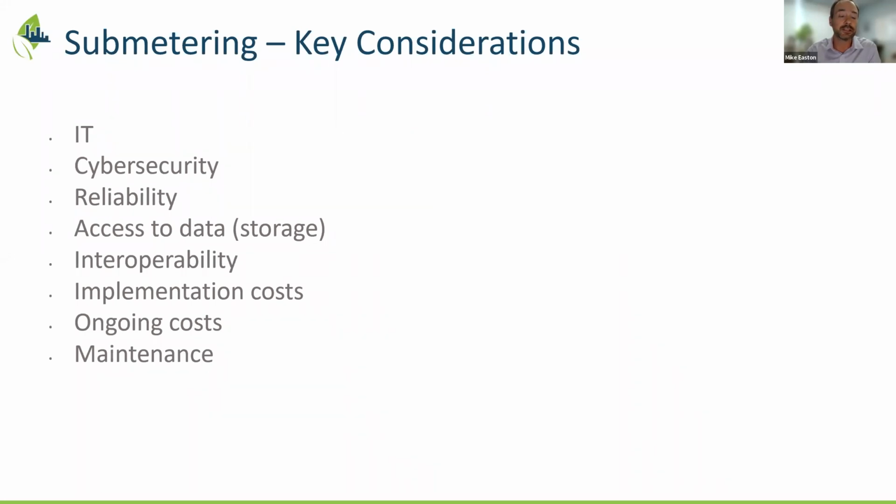which again seem to be very utilized these days. If you are going to be doing a web-based solution or getting the data out of the building, I believe the historic way that companies or properties have wanted to do it is utilizing the base building network. But we've really been finding this a struggle lately, whether it's an institutional portfolio or a commercial portfolio. Integrating with the base building network to hang metering on that is actually quite a challenge. So what we've really been moving our customers to is a cellular solution where the meters are completely independent of the base building network,